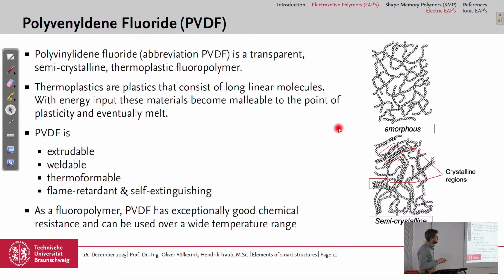So here we have the chain structure of an amorphous thermoplastic, and a semicrystalline one is a thermoplastic which has amorphous regions, but in addition also some crystalline regions here, and these crystalline regions we need for the piezoelectric effect.